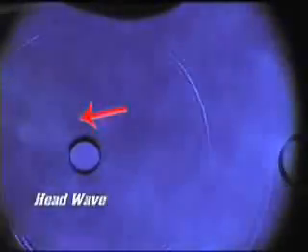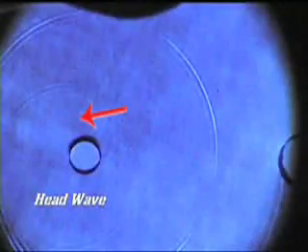The linked wavefront can be considered a form of head wave, and it has the appearance of a spiral. This head wave can be seen to account for the post-cursor signals that an ultrasonic technician sees as repetitions on the A-scan, as a result of several circuits around the cylinder.